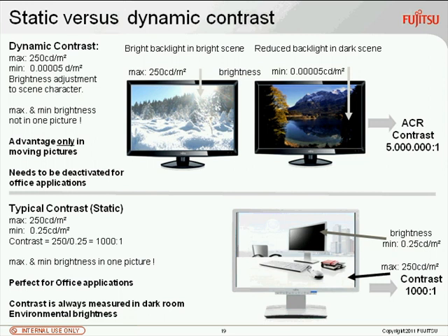That means you measure a bright point when the brightness of the display is blown up to 100%. Normally it's 250 candelas, which is the maximum brightness. To get the contrast, you also need the darkest possible point. I have to say the contrast is always measured in a totally dark room. So this contrast you never see in an office environment because you already have environmental light.